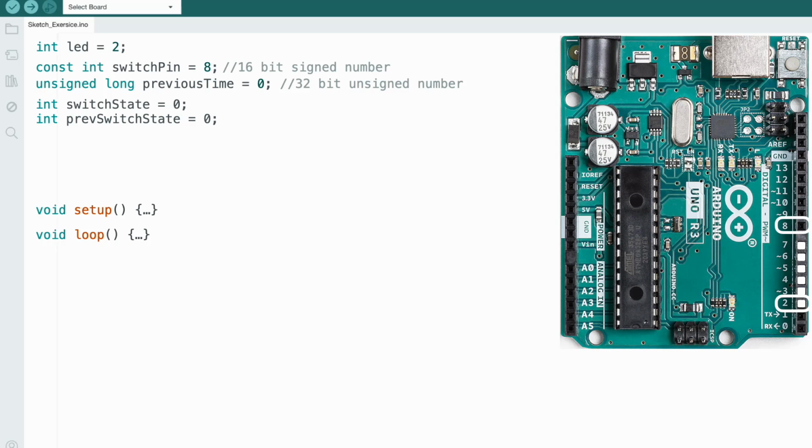And we're going to do a comparison of, hey, what's the latest value? Is that different than the previous value? Is the current angle different than the previous angle? And so that's all that we're using these switch states for, and that's pretty straightforward. But you will notice that they're both set to 0 the very first time, which is going to help us initialize the board and light up the proper LED in sequence.